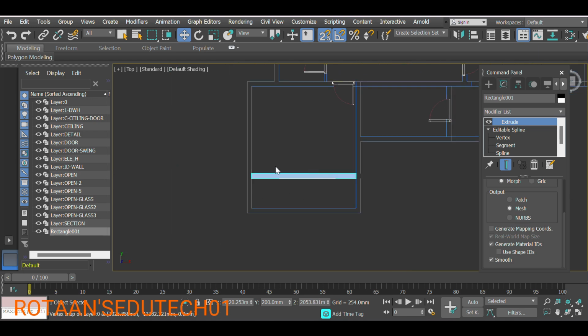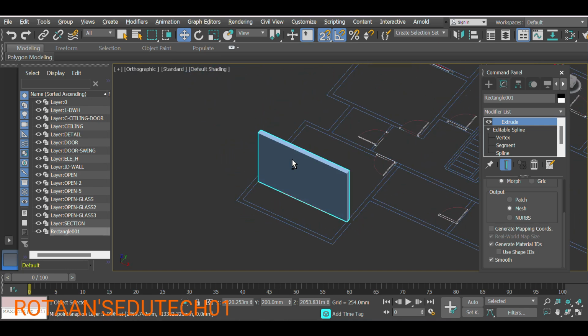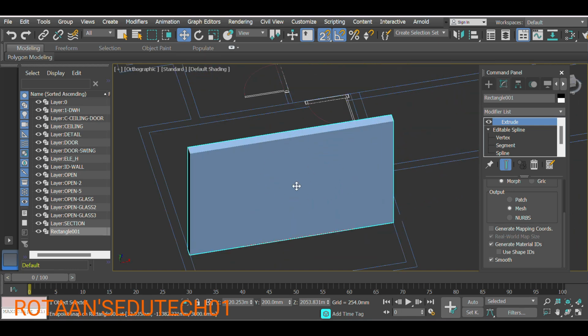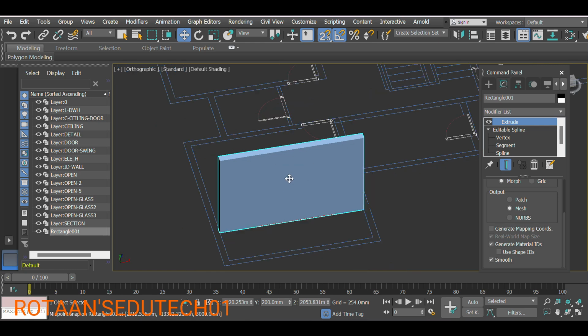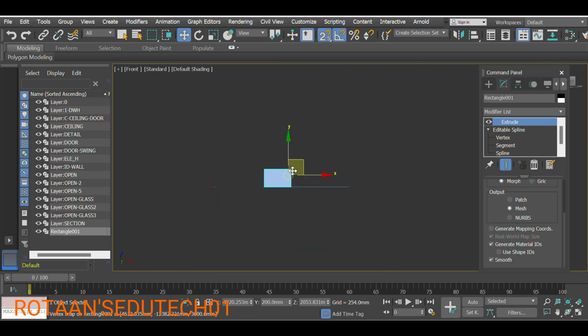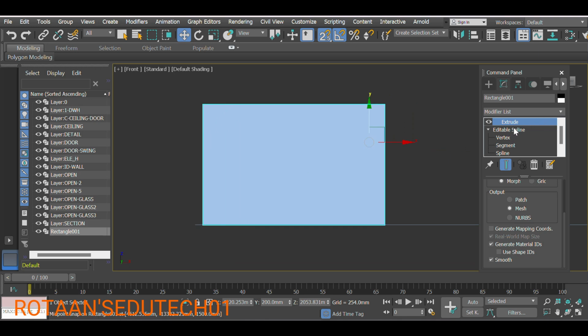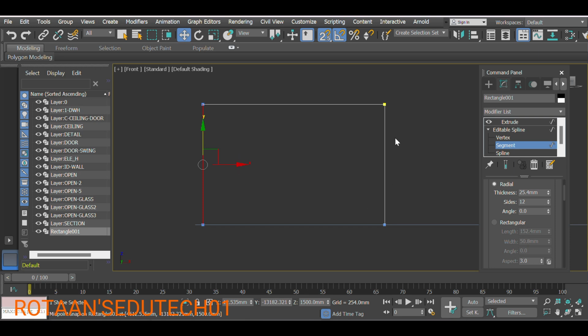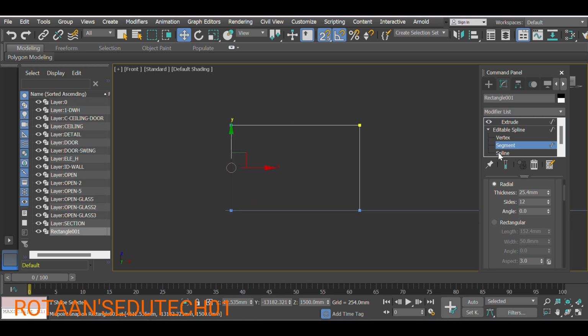Now what we can do here easily, I want a window here. Okay, so select this wall. Go to the front. Here if you again click on this segment, then it will directly come into the spline method. Getting it? Now this is very important, I'm just going to tell you, so you should focus on it. Spline, select, shift means I did copy.